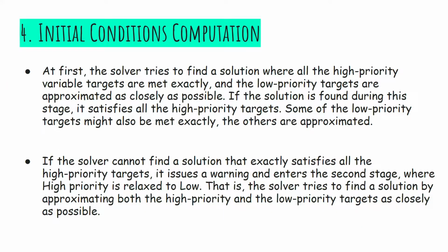The next step is initial condition computation. So the Simscape solver computes the initial conditions only once at the beginning, that is, time t equal to 0. In the solver configuration block, by default the start simulation from steady state checkbox is not selected. So if we select that checkbox, it will start the simulation from the steady state.